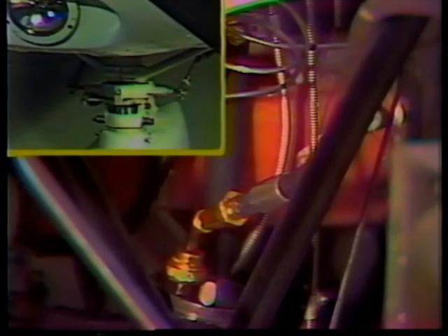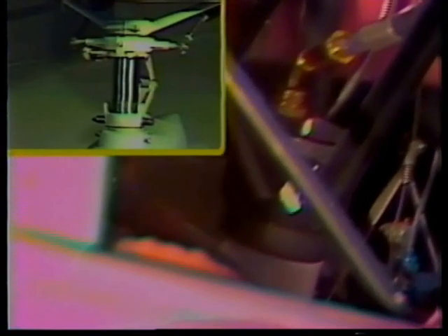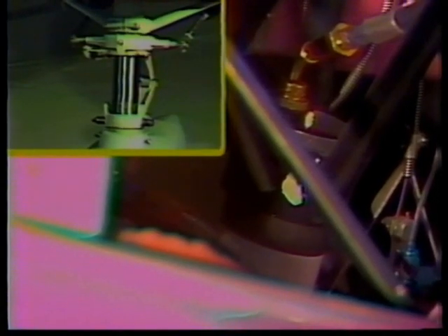Connect the nitrogen supply to the strut filler valve and carefully begin the inflation procedure. While inflating the strut, rock the aircraft gently to overcome packing friction and to avoid possible overinflation. When the correct amount of extension has been achieved, turn off the flow of nitrogen and disconnect the hose.